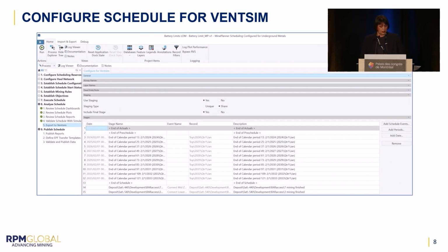There is also an option to auto-close dead-end stubs, and we can define a distance there. This is a distance from the nearest intersection to that dead-end stub. So as long as that is within the specified distance, it will auto-close.